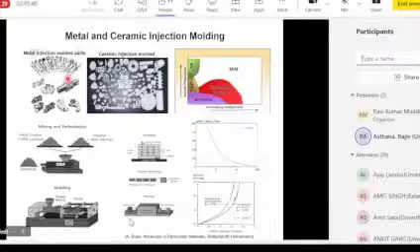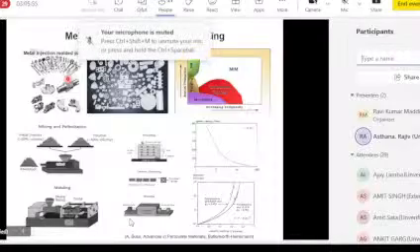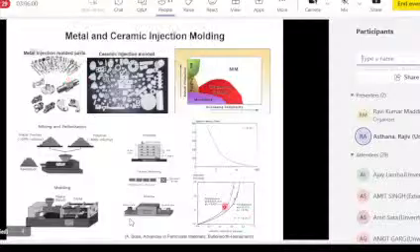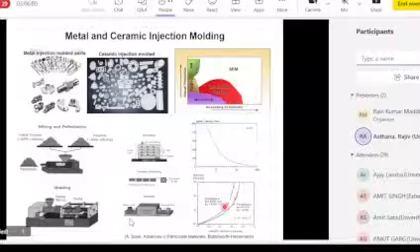And again, you can go into the rheology of the suspension and see how powder size and shape affect the viscosity, because the injection pressures here will be higher than the injection pressure used for just polymer. If you were injection molding polymers, you would use lower pressures. Also, the conductivity of the part is changed because of ceramic or metal powders, so the cooling process has to be considered. So I think I'm not going to go into these details here.